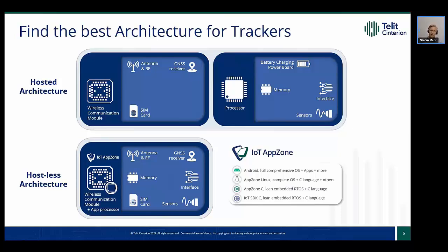On the lower part, you see a hostless architecture. That's a good way to get rid of this extra CPU. Here, all the logic and intelligence is running on the module. We offer an environment to run the application software on Telit modules. This is called IoT App Zone. It starts from a small real-time operating system with C language and goes up to smart modules with a full Linux and Android environment.